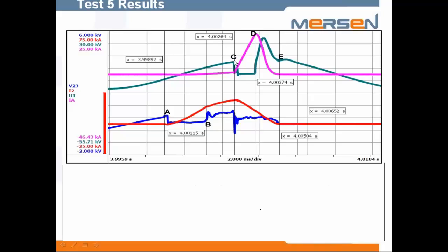At some point, the switch closed, and this is about 4 milliseconds later, and when that happens, as shown, the voltage on the primary side goes to 0 very rapidly. The current, which was rising to 700 something amps, now rises to the available fault current, which is well over 36 kA. And at point D, the fuse melts. And it was shown earlier, the voltage quickly rises, you have a voltage transient, and at point E, current is out, and now the voltage is back.